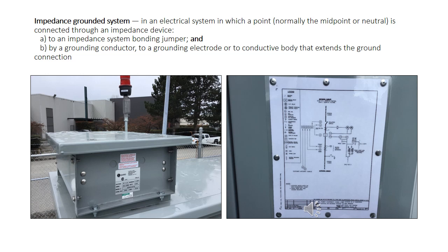The advantage of this is much like a delta system, but it contains a neutral conductor. This is used in heavy industrial situations where a ground fault will not trip the overcurrent device, but also trained maintenance people are on staff to fix any problems. The photo on the right is of a one-line diagram, which is critical to keep and maintain on a work site.